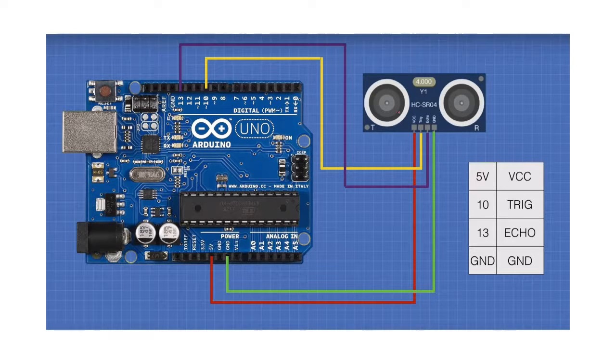You can see that this is the sensor we are talking about, and the T transmits the sound. The other side is usually the R that receives the echoes that bounce back to the sensor. As it receives, we are able to identify the distance between the object and the sensor, whatever the obstacle is. And this is how we connect it.